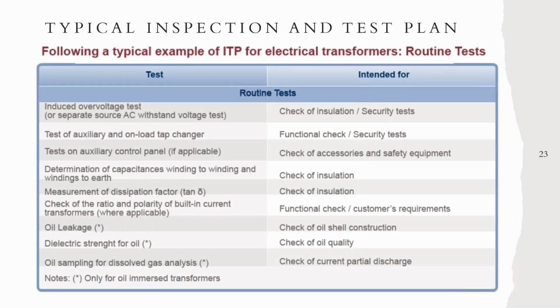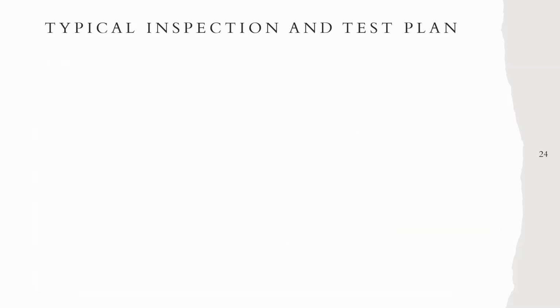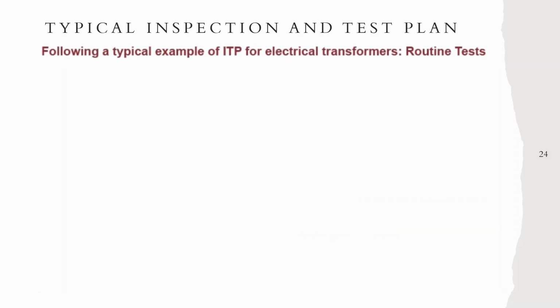Test of induced voltage, auxiliary, on load tap changer, test of auxiliary, determination of capacitances, measurement of dissipation factor, oil leakage, dielectric strength, oil sampling for dissolved gas analysis. This is for the test, and this is the purpose.